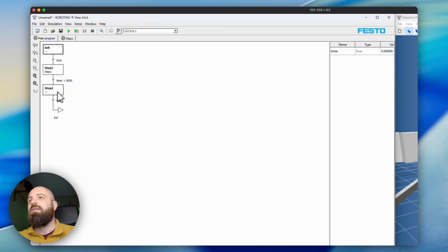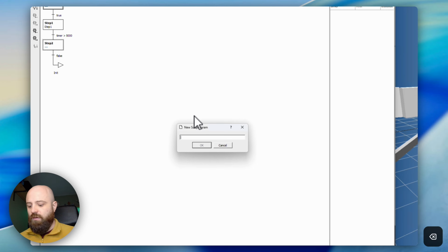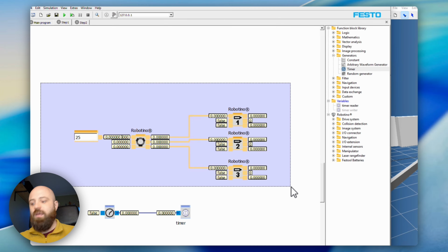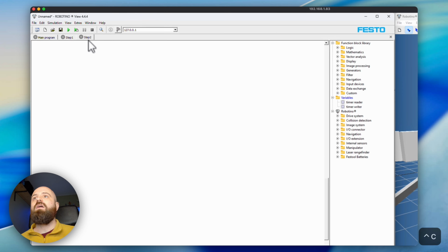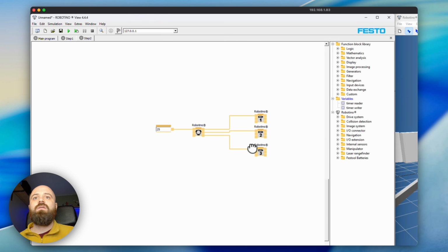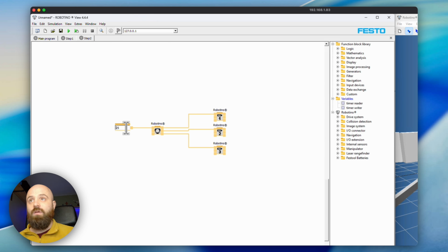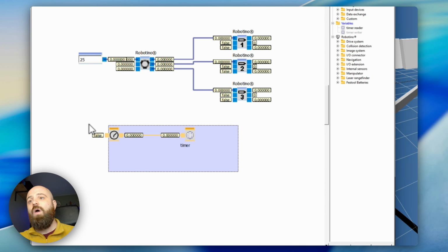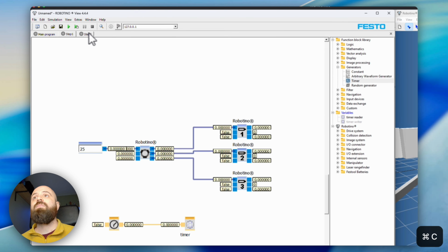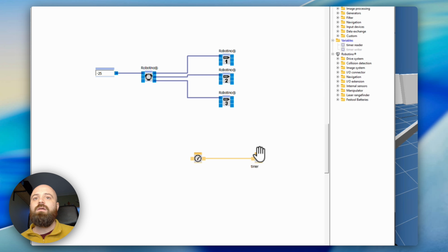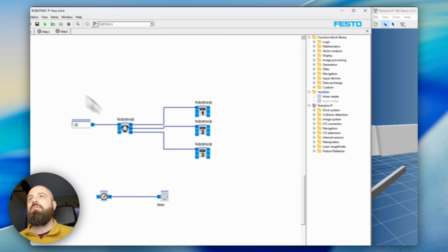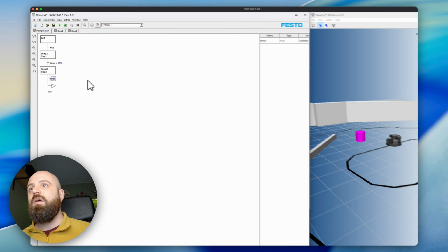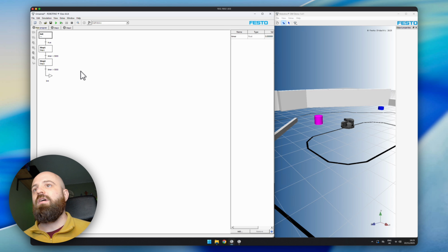That's the idea here. Now what's in step 2 at the moment? Nothing. We could create a new program called step 2 and we could copy all of the program execution code into this one, and I'm going to set this to -25. We want the Robotino to go backwards. And actually we could do the same thing again here. We could use exactly the same timer because it's a global variable, it's available within all of our steps. And so we could say what we want it to do is check again if it's greater than 5,000.